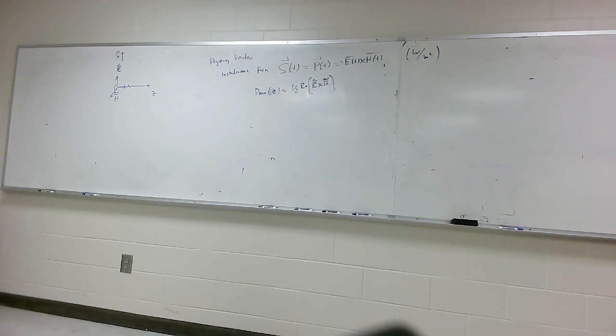Now, if you have an inductor and it has current flow in it, then you have a magnetic field. The magnetic field is all around, theoretically. It's concentrated near the coils, but it is not propagating. And all the energy in the magnetic field can be gotten out. The magnetic energy the inductor has is 1/2 Li squared.